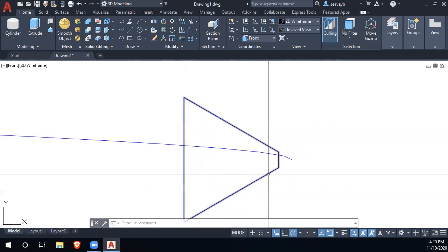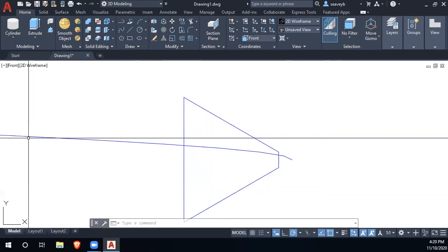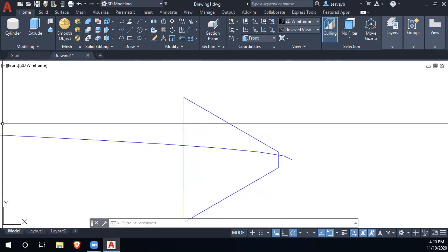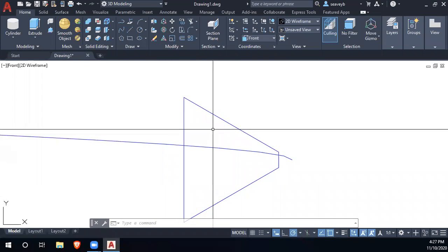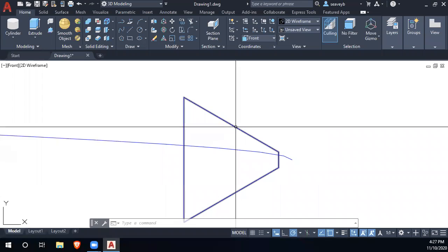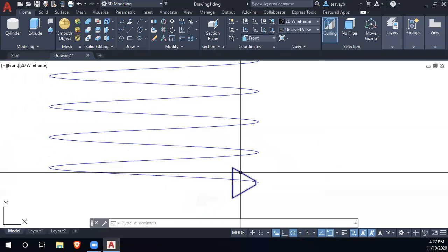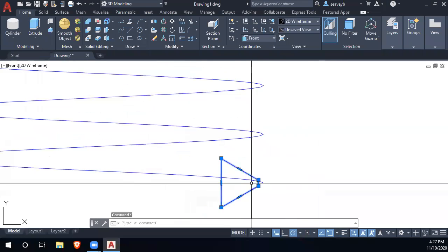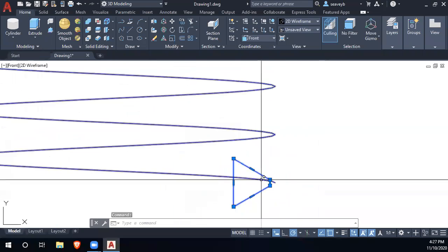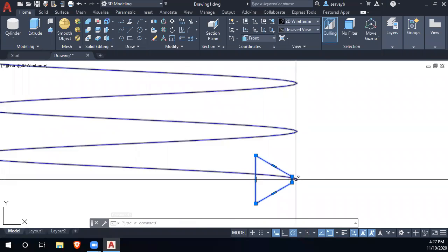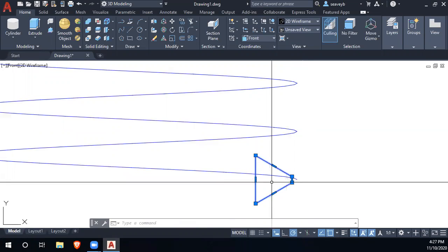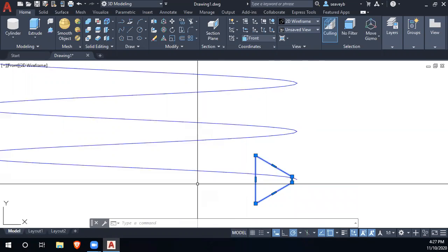Is that all right so far? Pause. So we're going to use the sweep tool. I'm not even sure which to select. I think I can just select the triangle shape that's been joined together. So now it's a single polyline and it's in the right position. It's a little bit less than 5/8 out there, as far as diameter goes.